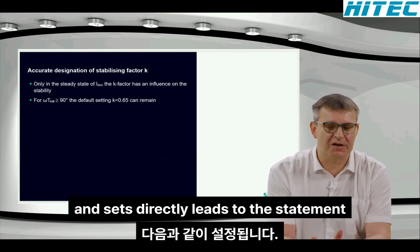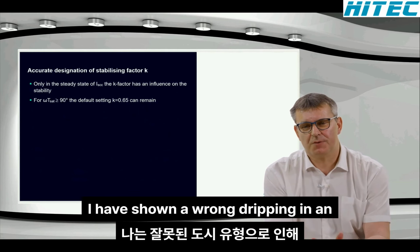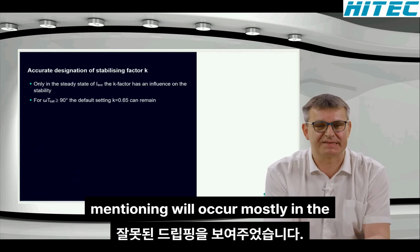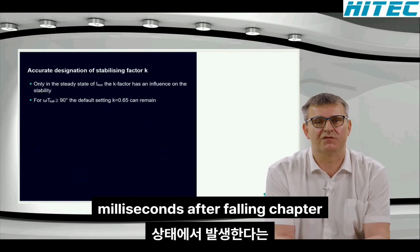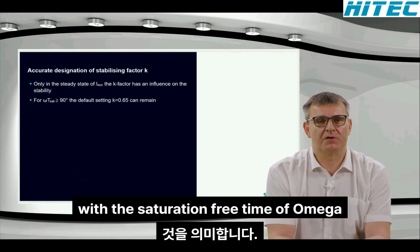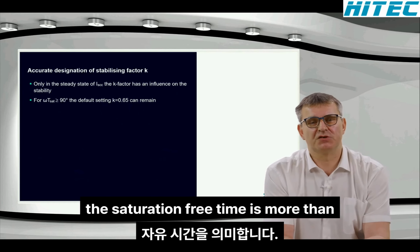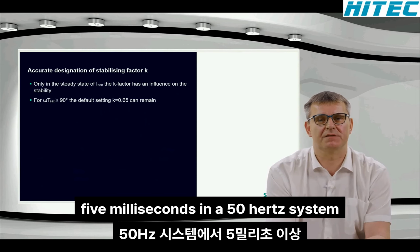And that directly leads to the statement I have shown: a wrong tripping in an external fault due to wrong CT dimensioning will occur mostly in the steady state, meaning it will happen 100 milliseconds after fault inception, with a saturation-free time of omega multiplied with tsat more than 90 degrees, meaning the saturation-free time is more than 5 milliseconds in a 50 Hertz system.